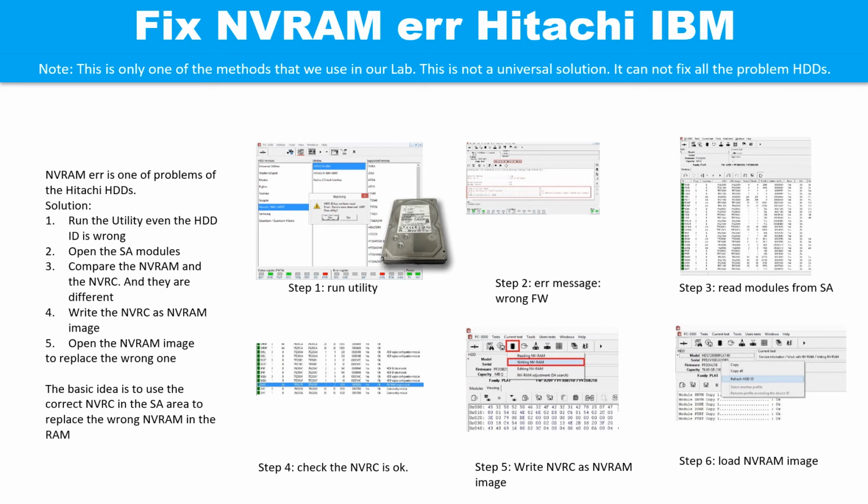Step-by-step solution. Step 1. Turn off the power supply. Isolate the actuator contacts on the PCB. Step 2. Turn on the power supply. Step 3. Perform soft reset or hard reset. Step 4.